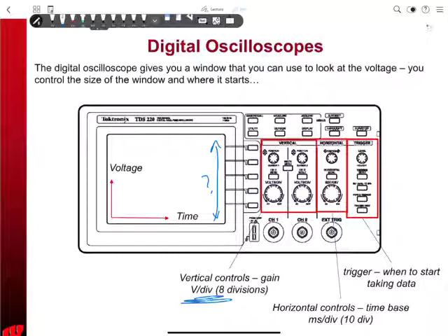Also in the time, I need to know how wide this window is, right? If I'm measuring heartbeats, say, if you're looking at an elite endurance athlete, their heart might only beat 30 or 40 times in a minute, right? Which means it's a second or two between beats. So I might need a full second there. Whereas if I'm measuring the impact on a crash test dummy, I might need milliseconds there. So I need to adjust how wide that is, and that is the time.